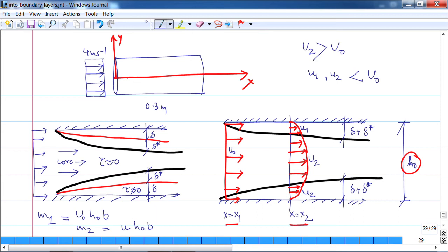So, therefore, this question, how does the centre line velocity accelerate, or what is the acceleration? The first question is why will it accelerate in the first place? So, this is the reason. You could also look at the displacement thickness another way: it is almost like an extra thickness of the wall itself, almost like behaving like another layer, a thick wall.